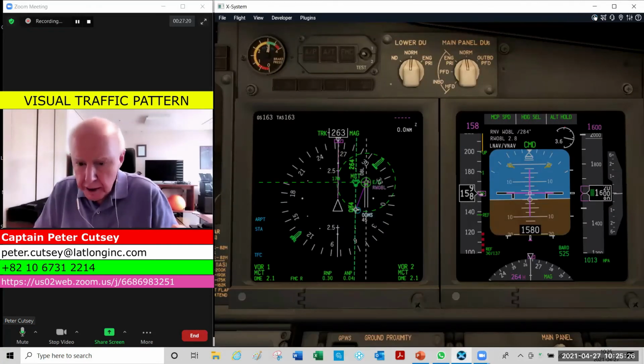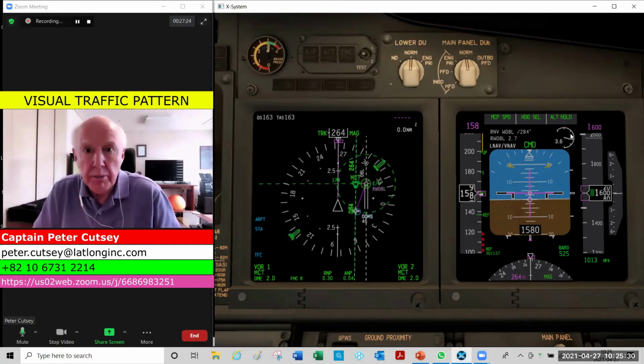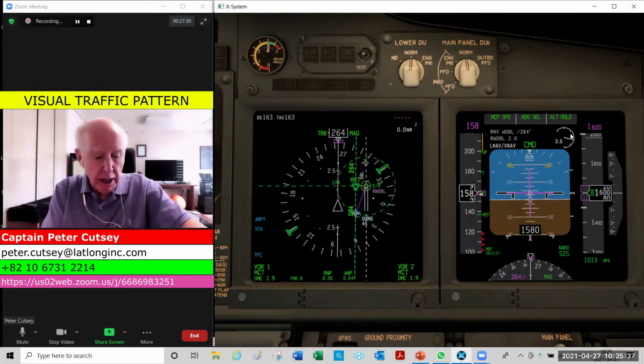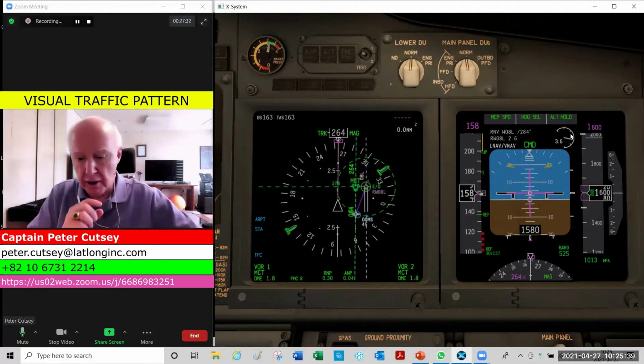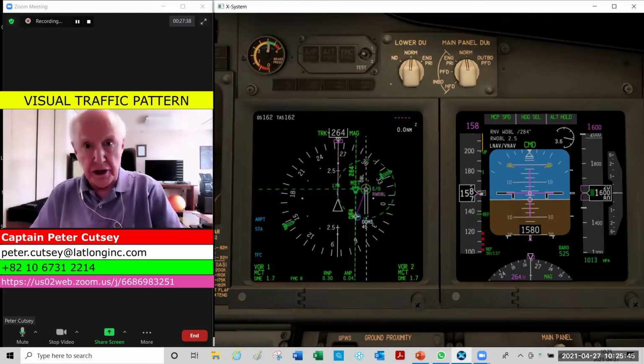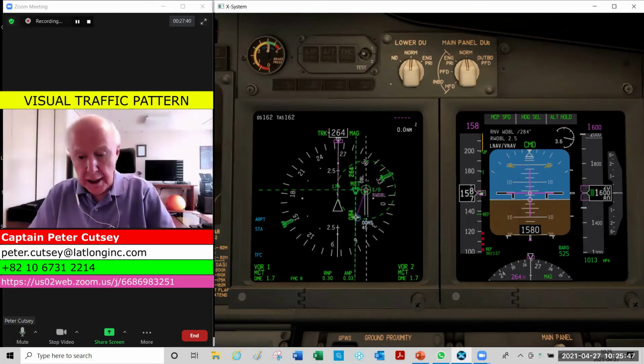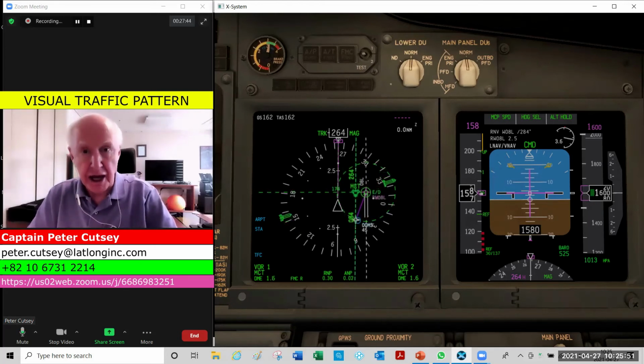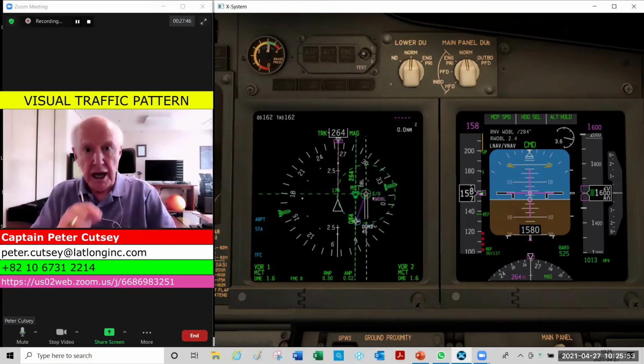So we're downwind, and we'll go dynamic again. And when the abeam radial, 174 radial, is halfway through the aircraft symbol, we'll start a timing. And we'll do that with the clocks on the aircraft. I'll use my chronometer here. And nothing in the first 20 seconds, as we mentioned before. And then at the beginning of the second 20 seconds, gear down, flaps 15, and speed brake arm.